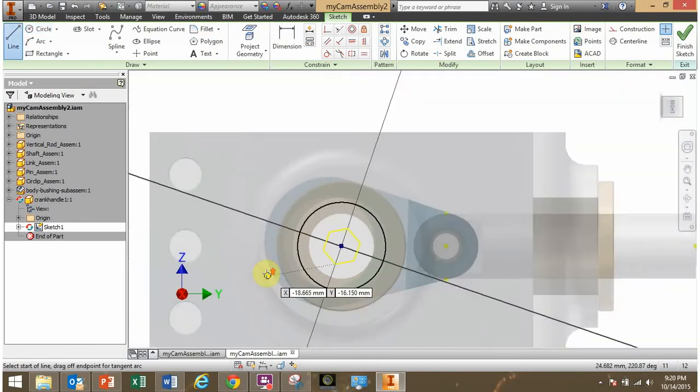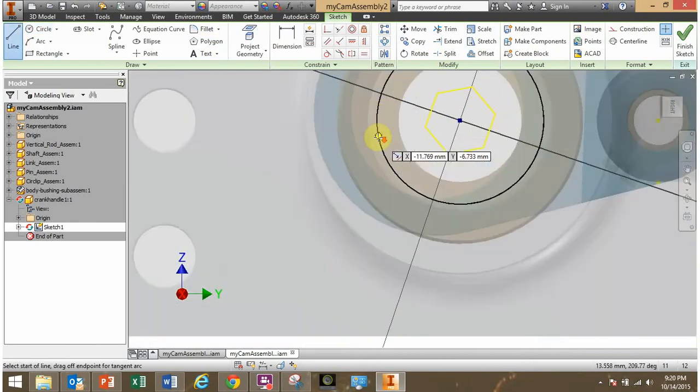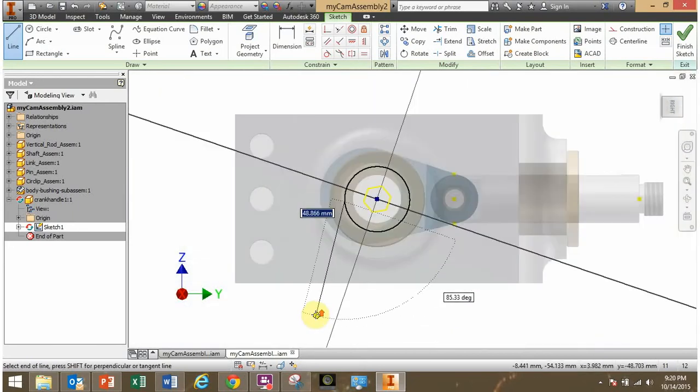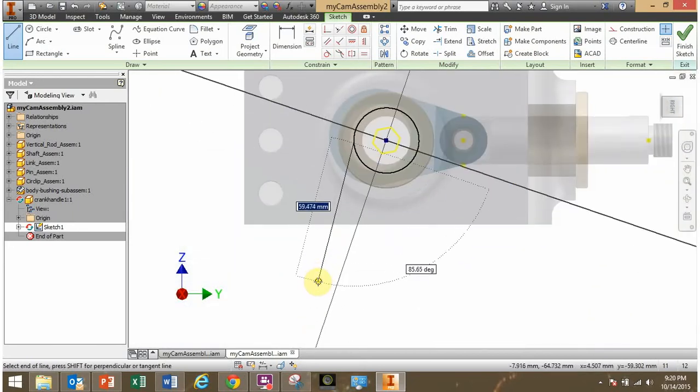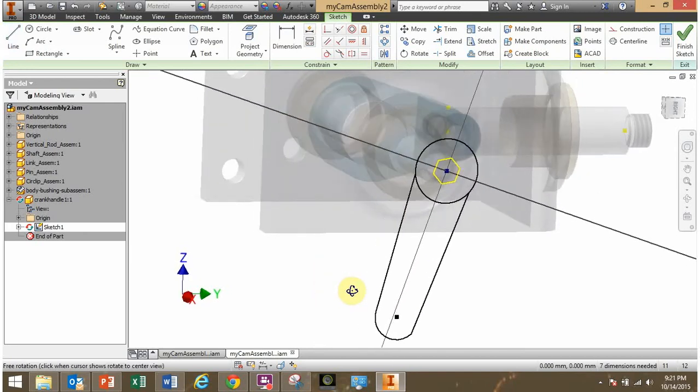Now let's create a line. I want it to get on the circle here. So snap to the circle. I'm going to come out here, click once, and I'm going to click and hold so I can make a little semicircle there. Release my mouse button and then come up here and click on that circle. Okay. Now it's not exactly good geometry yet, but that's okay.